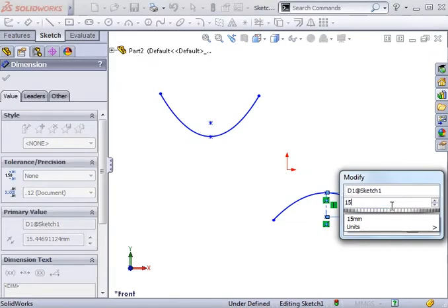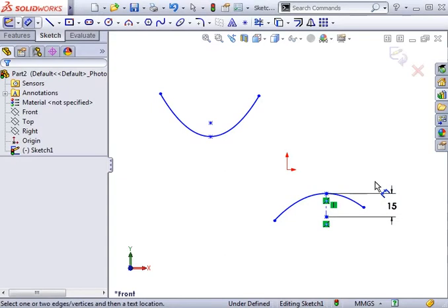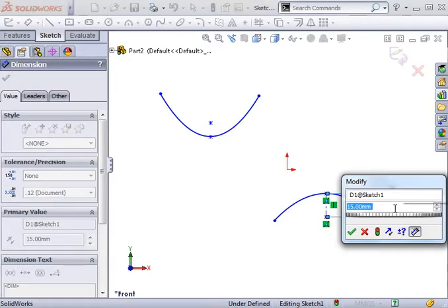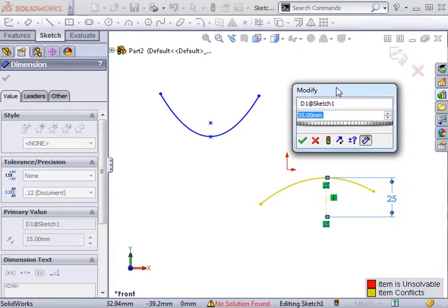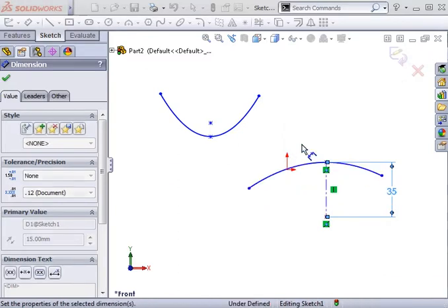Making use of the parabola even more intimidating to some users is a bug that exists as of SolidWorks 2005 Service Pack 0.0. As you make changes to the dimensions that control parabolas, SolidWorks has the bad habit of reporting invalid or unsolvable solutions. Your sketch will become yellow or red, indicating there are errors. However, if you accept the dimension, the error will go away.